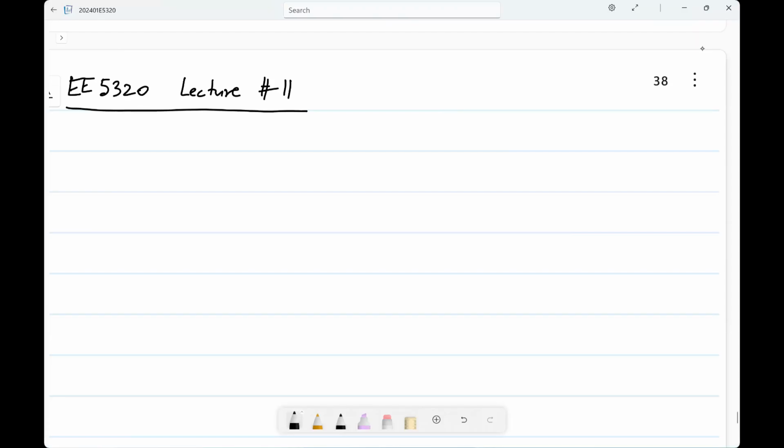Okay, because when you have noise, the noise will be represented as an additional small signal source. Okay, so all you need to know is incremental analysis, which is linear, right? And in fact, we will see it's exactly the same as how we analyze circuits for mismatch, except mismatch is also represented by an additional source. These will be similar sources.